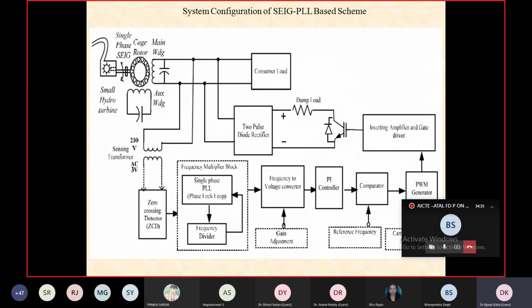So by reducing the size of the capacitor in the output of the single phase rectifier, you help the power system community. So you should try to reduce the value of capacitors connected in the output of the rectifiers, unless and until it is required. So as a designer.